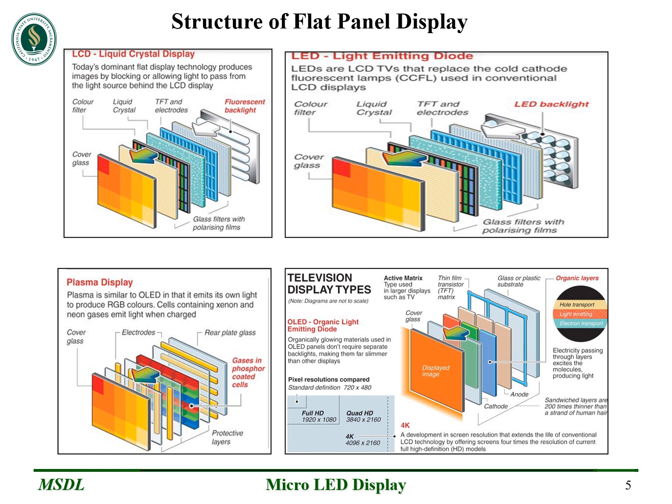The next display type, LED, is actually a bit more known, because an LED display is just an LCD display panel with an LED backlight instead of a cathode backlight. This gives a couple of advantages. Number one is lower power consumption. Number two is an even thinner form factor because they are not nearly as bulky. Number three is that with many high-end LEDs arrayed at the back, you can enable a feature called local dimming, so that where the LCD goes black, the LED behind that zone can turn down or turn off to make the black more true and much more rich.